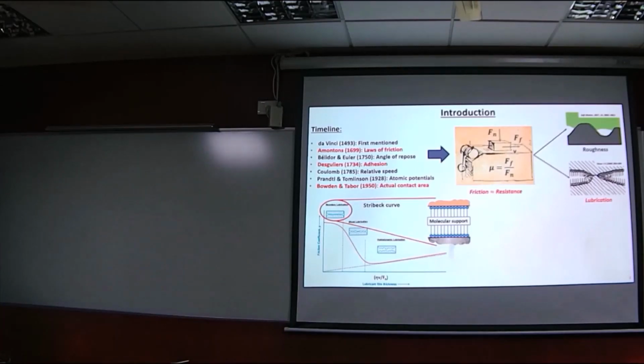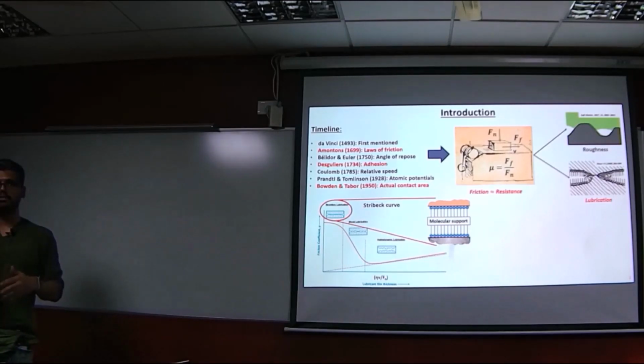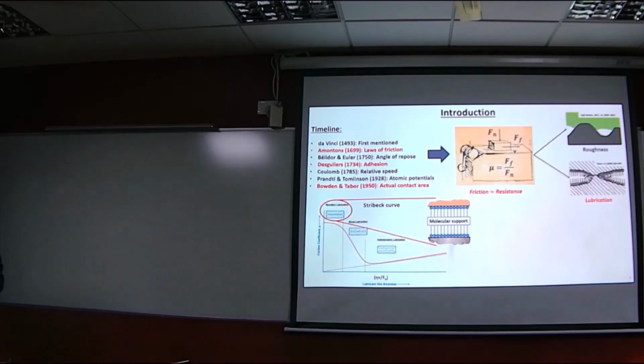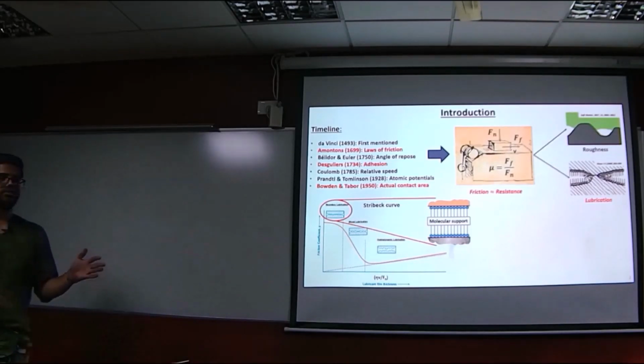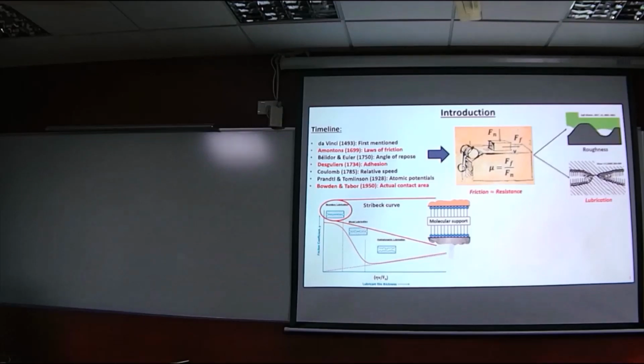The sole properties which affect friction in this particular case are the interfacial properties. So anything present on the interface has the potency to change friction. The characteristic thing is that out of all these regimes of lubrication, it has the highest coefficient of friction because many of the asperities are directly in contact, as opposed to thick or hydrodynamic film lubrication. So it is the molecules resolved onto the interface that are providing lubrication and not the bulk